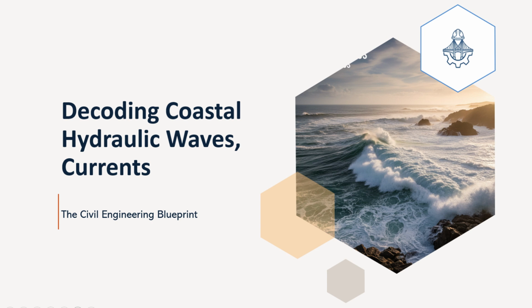And from this energy conservation principle, we can derive the shoaling coefficient Ks, which directly quantifies how the wave height H changes relative to the deep water wave height H0 during shoaling. That's right. Since E is proportional to H²Cg, the energy conservation equation becomes H0²Cg0 = H²Cg. Rearranging this to solve for the ratio H/H0 gives us the shoaling coefficient, Ks = H/H0 = √(Cg0/Cg). This equation is vital because it tells us, for a given deep water wave, how tall the wave H will be at any shallower depth before it breaks, assuming only shoaling is happening.